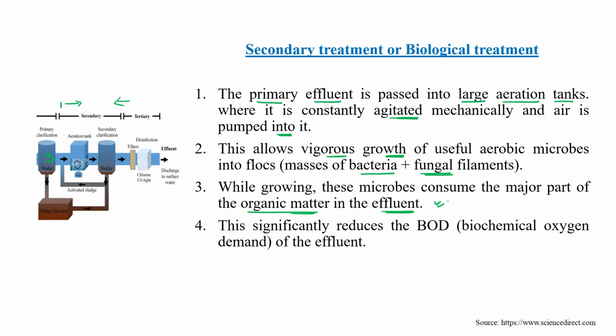And then what will happen? Because of the consumption of organic matter, it will significantly reduce the BOD of the effluent, meaning biological oxygen demand, because most of the oxygen present in that effluent is utilized by the bacteria and fungus for their growth. When they utilize this oxygen, this process significantly reduces the BOD of the effluent.